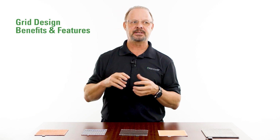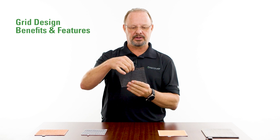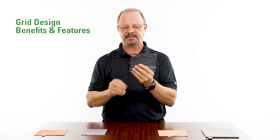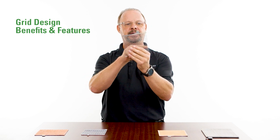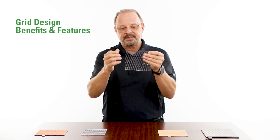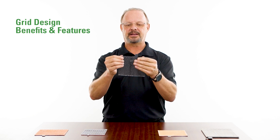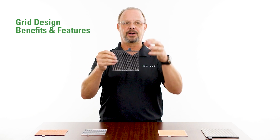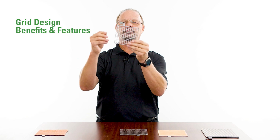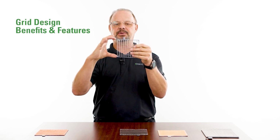So expanded grids have better active material adhesion, and the downfall that people often speak about is that they're not a full frame grid. So as the grid gets older or the battery gets older, there's a tendency, because batteries are alive, they'll grow. This positive plate wants to push up on the corners. With a full frame grid, you've got a frame down the edge here that kind of keeps that structurally intact.